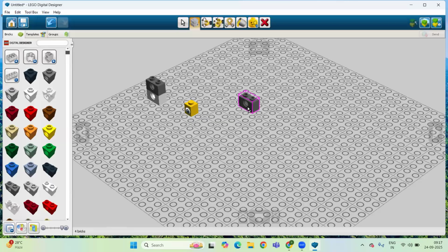Got it? What do you have to do? Left click to place the clone. The main tip is you can continue placing multiple copies until you change tools. If you do the same thing once again, clicking and dragging your mouse, you can continue creating multiple copies until you change tools.